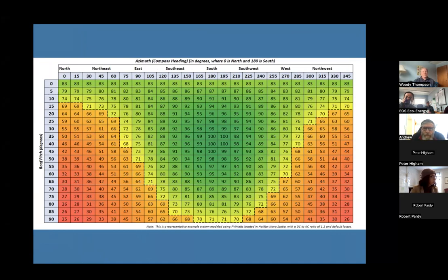About 2016, Nova Scotia came out with substantial rebates on residential solar installation. As a result, suddenly the number of companies installing solar multiplied, and they ran into some substandard installations. So they had to create some parameters about the orientation and tilt of the solar array. Their requirement is that in order for a solar array to qualify, it has to be 70% or greater of the potential output that you could get.